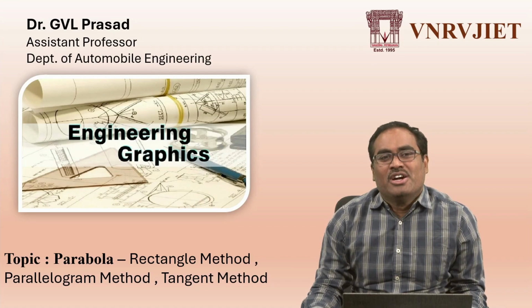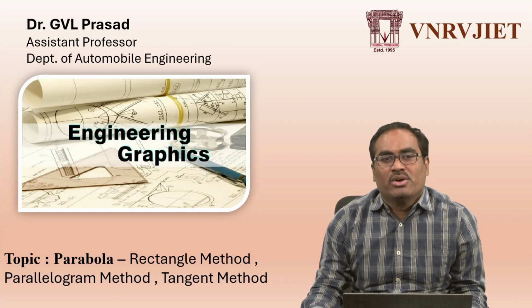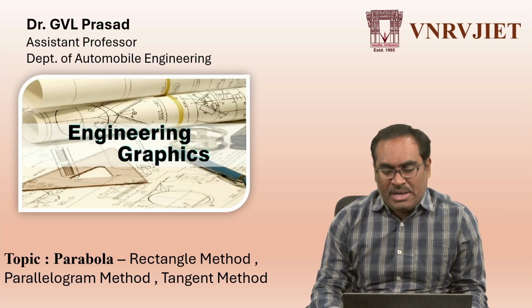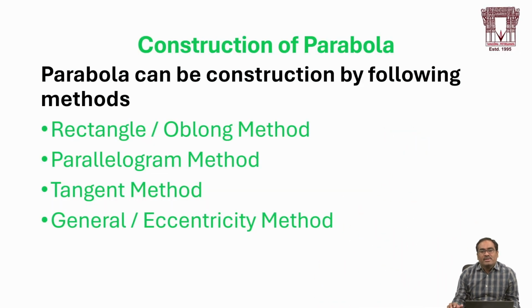Hello everyone. In this video, I will show you construction of parabola. Let us go to the various methods of the parabola. A parabola can be constructed by the following methods: rectangle or oblong method, parallelogram method, tangent method, and general or eccentricity method. In this video, I will show you the first three methods: rectangle, parallelogram, and tangent method. So let's go to the problems.